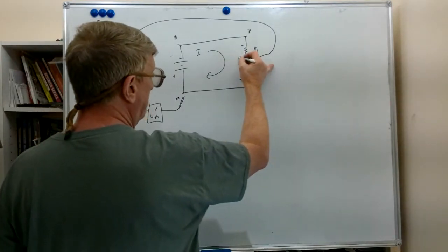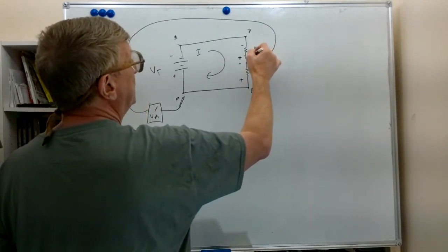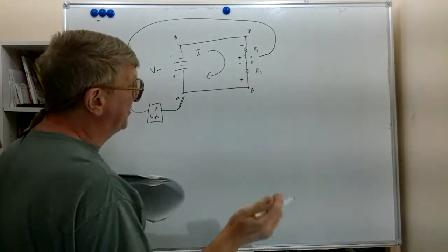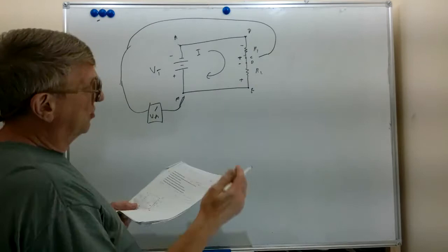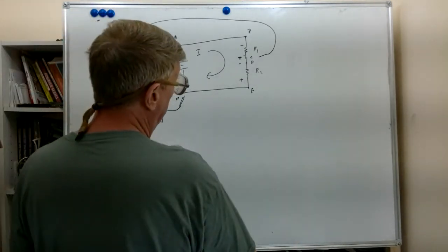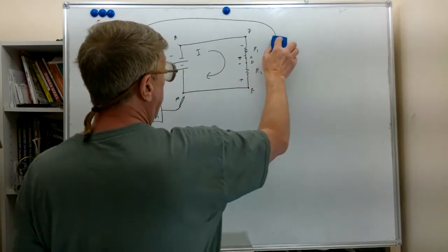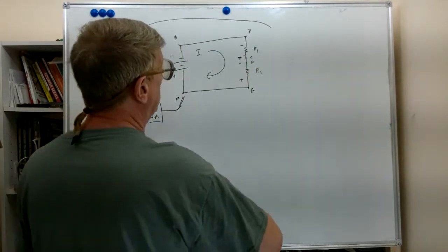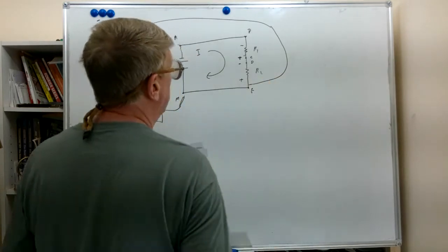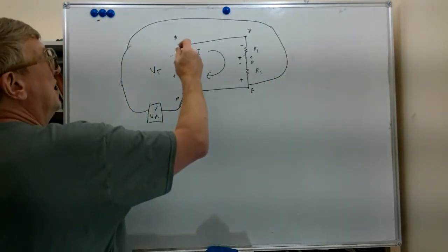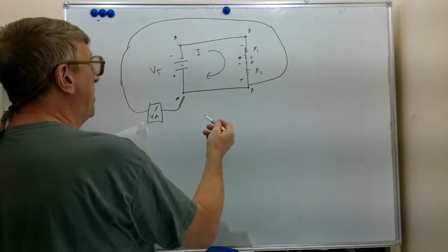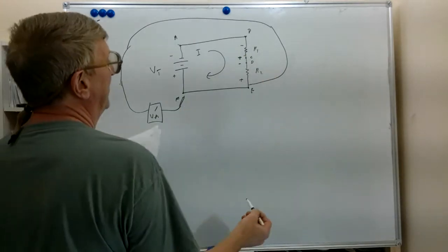So that's basically what we saw across the voltage drop of R1. We became a little more positive as we went across it, or a little less negative, depending on how you want to look at it. And if we move our meter to the next point, E, the same thing happens. As we get closer and closer to the positive terminal, we become more positive and less negative.